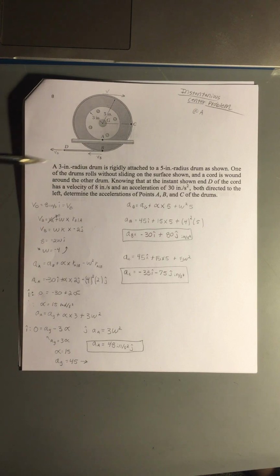Looking at the circle, we can also say that the velocity at A will be 0, not the acceleration. And because of that, we can say that this is the instantaneous center of zero velocity, and so that's a point we can use quite a bit in our calculations.